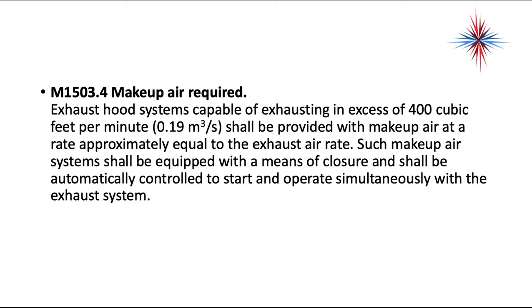Now, in most residential kitchens, you will not hit the 400 cubic feet per minute unless someone has installed a commercial or a high-end exhaust hood. You see those big exhaust hoods over the larger gas ranges. It's very possible that that could hit 400 cubic feet per minute. You have to bring in makeup air.